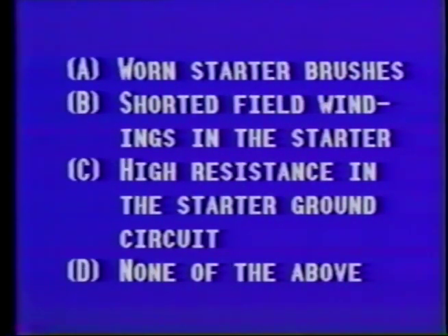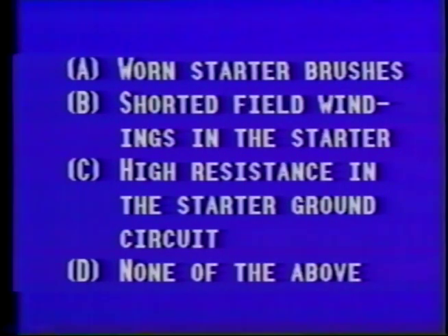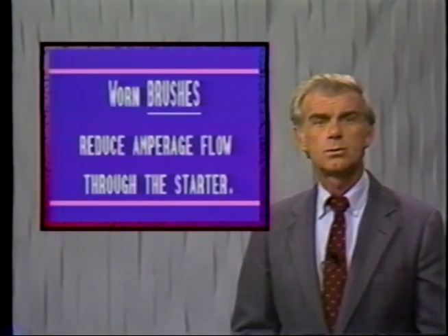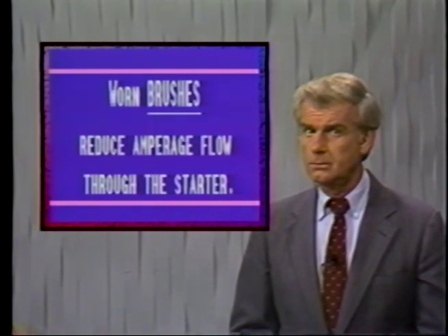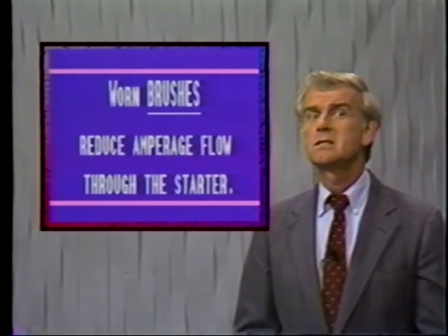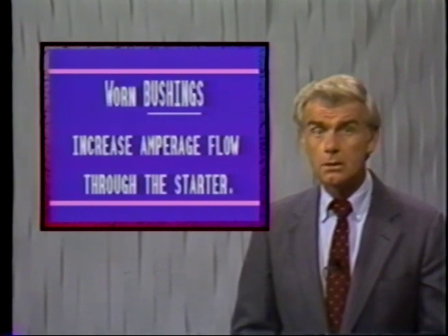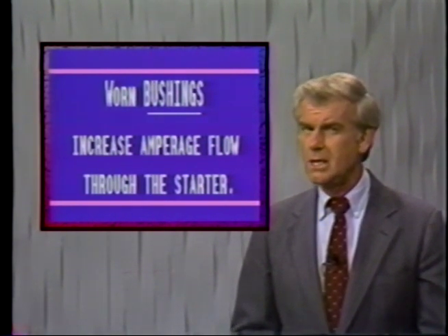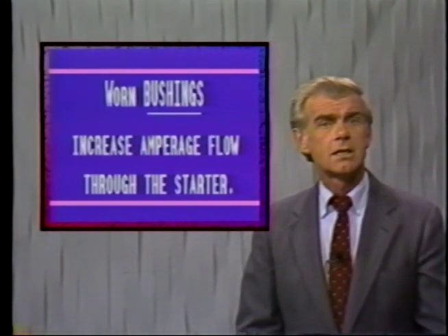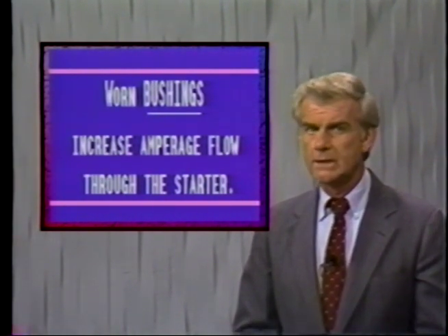Looking at our choices, response A suggests worn starter brushes. That's right, brushes, not bushings. Worn brushes would reduce contact with the commutator, lowering the amperage flow through the starter. Yes, if the response had said worn bushings, then it could have correctly answered the high amperage draw scenario. Read carefully. Obviously, response A can be ruled out.